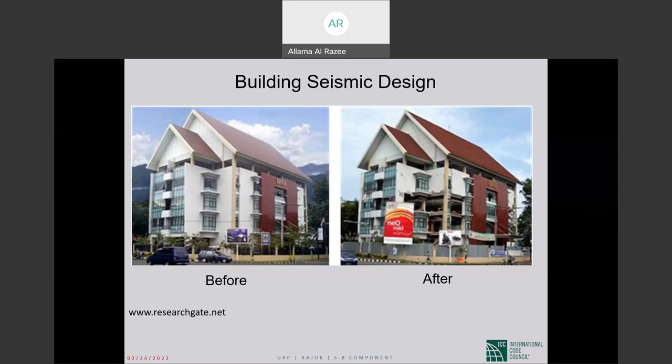So again, for the extraordinary load, such as blast, such as earthquake, the design level for earthquake, usually most of the codes around the globe assume an earthquake with a return period of 475 years as a base for design. Although this earthquake is not a very huge earthquake, a 500-year return period for earthquake is not that much.